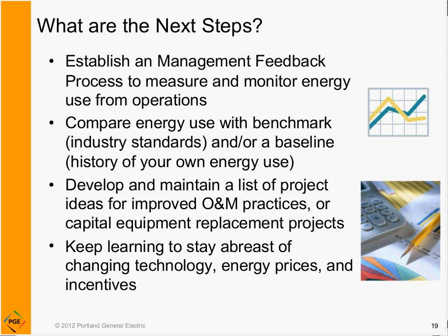Compare energy use with benchmark. Our staff here produces benchmarks of what should a typical office building use, what should a typical restaurant use in energy, both gas and electric. Give us a call and we can share those benchmarks with you, and you can compare your building with that benchmark. If you're high, you may start asking questions about why is our building using more energy than a standard or average building. We talked about developing and maintaining a list of project ideas.